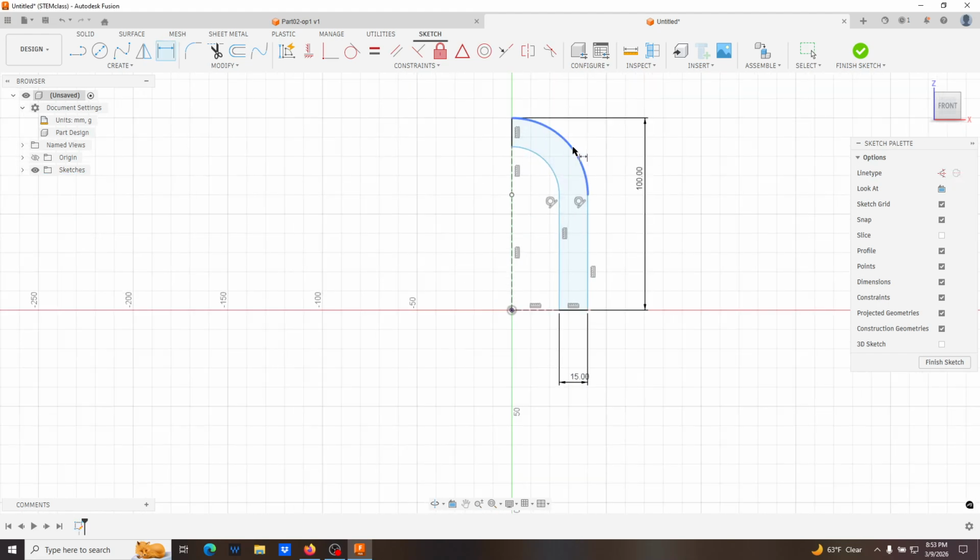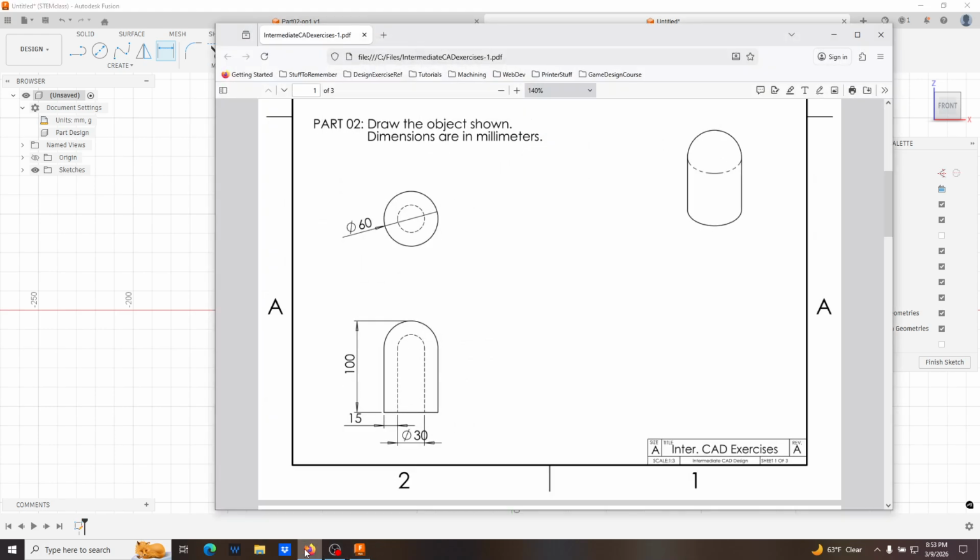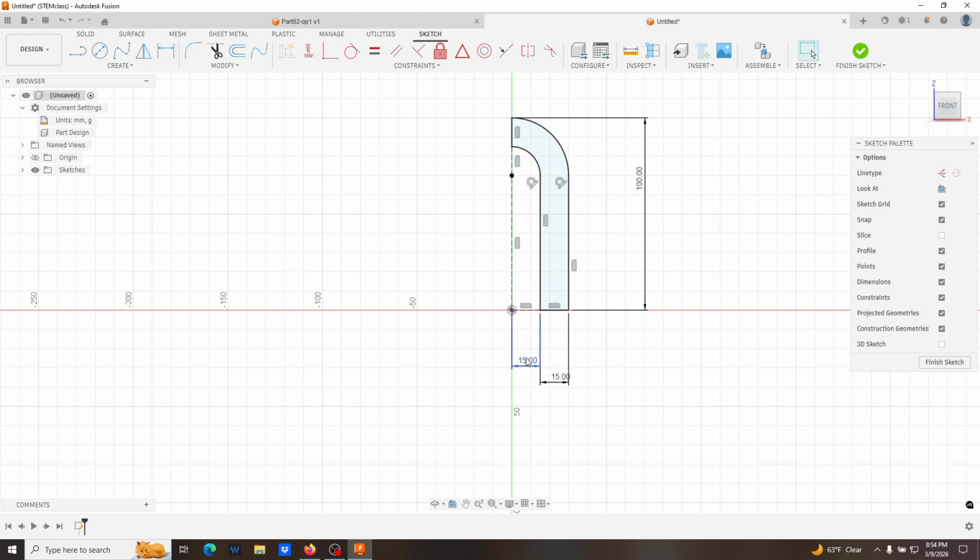And then what's interesting is that I could go ahead and put the radius here as a defining dimension, but because of how I've defined all of this, if I go down here and I make this, is it 15? You'll see that everything turns black as if it's fully defined. Yeah, that's 30 in there. So just to demonstrate that, if I go up here and dimension, and I make that 30, it's the same information given different ways.